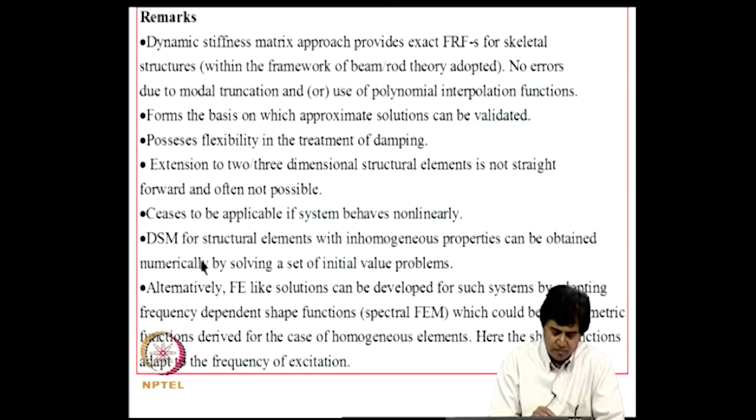Now again, if structural elements are inhomogeneous, with spatially varying elastic constants and so on, it is possible in principle to develop the elements of the dynamic stiffness matrices by solving a set of initial value problems, but that would bring in some approximations. Alternatively, after going into the frequency domain, finite element like solutions can be developed for such systems. By such systems I mean inhomogeneous, linear time invariant problems.